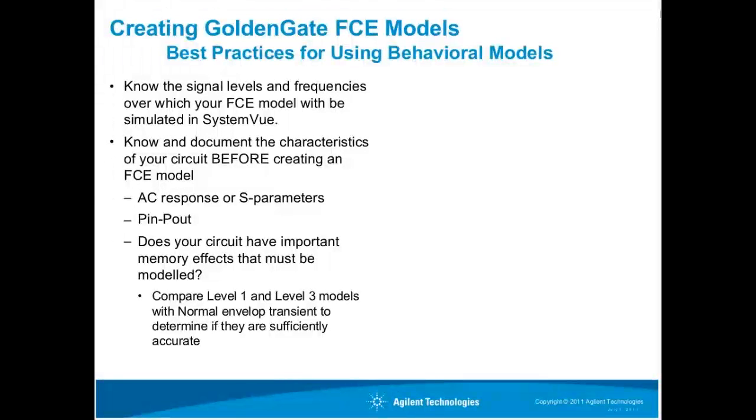So, I recommend that you at least know the AC response of your circuit, the compression characteristics, and you really need to know if the model has memory effects, which is something that's not so easy to do, but maybe you have to run some envelope sims to find out.